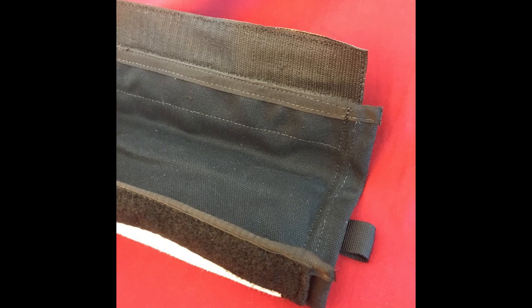Second, sections of discarded fire hose. Older hoses were made with a cotton jacket over a rubber core. By slitting the hose lengthwise, you could create a secure pad. The rubber side goes against the edge, the rope rides over the cotton jacket. Minimal slipping, and it's surprisingly effective.